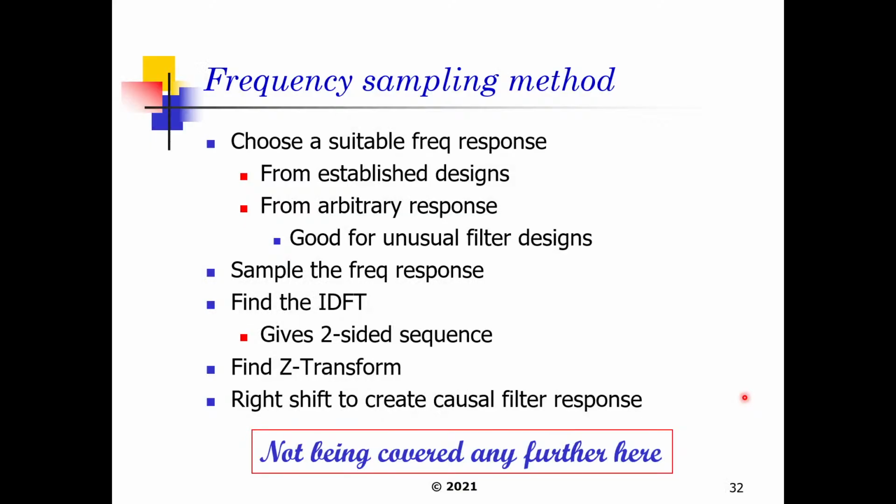Alright, so just to do a little brief recap here, we saw that for symmetric sequences and applying any delays for symmetric sequences, we maintain that constant linear phase behavior relationship, which was discussed at the start of the lecture. And this is important for when we go about designing FIR filters, because when we need to move from an anti-causal form to a causal form, by applying these delays accordingly, we see that we don't affect the phase behavior of the filter design itself, as well as the phase behavior of the signal that is being filtered. We also note that the only thing that's being affected when we do this is going to be the magnitude, but the magnitude, as required for distortionless transmission, is also going to be affected such that there's a uniform attenuation as required. The phase shift that we also observed there was also a uniform phase shift such that all the frequency components in that signal were affected uniformly by one multiplication, one addition or one subtraction of the delay factor accordingly for the phase.